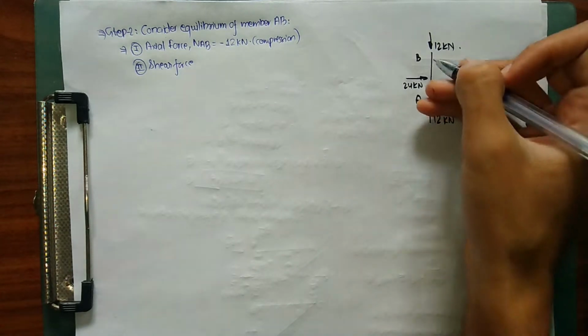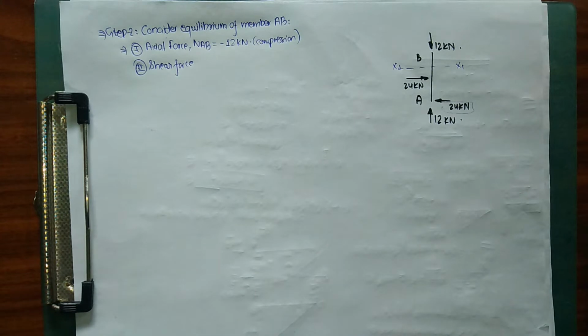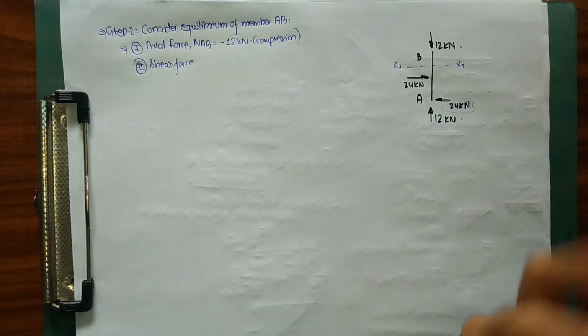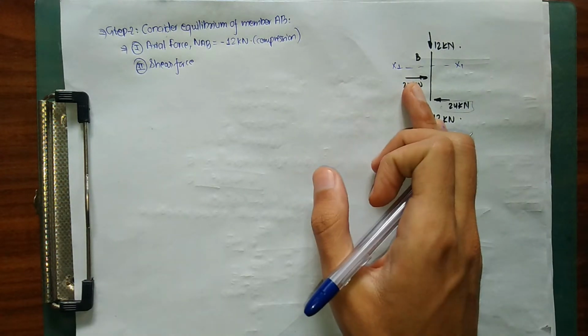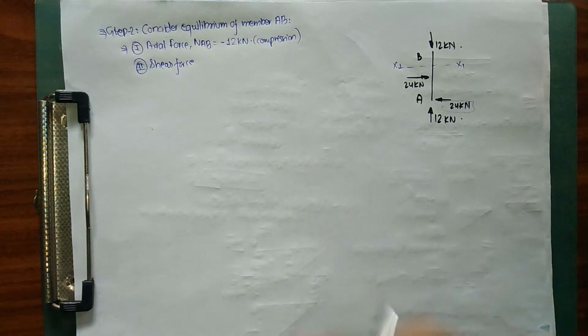We can either take a certain section x1, or we can calculate it directly as well. So I'm going to do both in order to make you understand clearly. Firstly, while taking a certain section x1, I need to be careful about where to take our section. We need to take our section x1 at such a length that it takes up much of the forces acting on it.